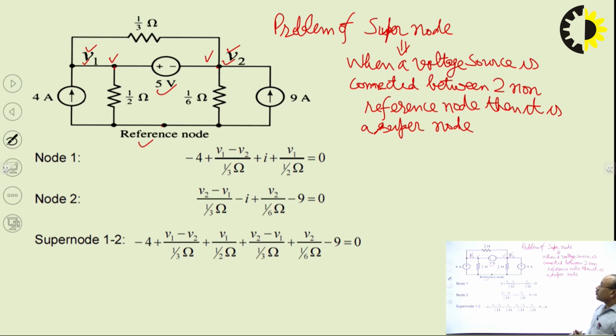So now we are to solve this circuit using the nodal analysis method. So again we apply KCL at different nodes where we are to find node potentials. So we will apply KCL at this node where the node potential is V1, which is unknown for us. Similarly, at this node where the node potential is V2, which is also unknown for us. So at V1, this 4 ampere current is incoming current.